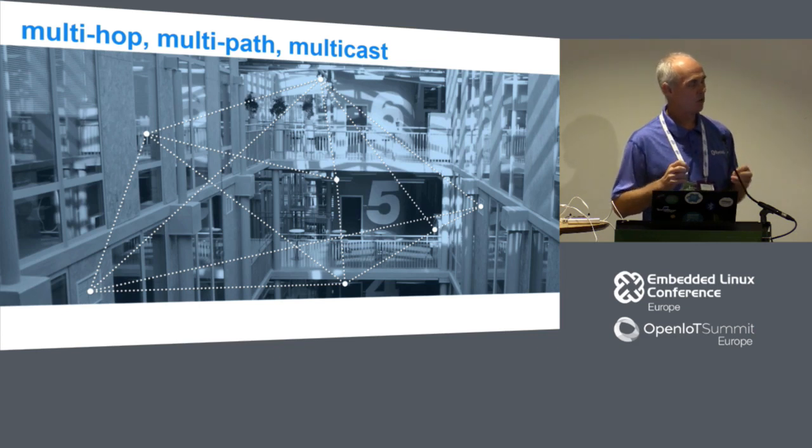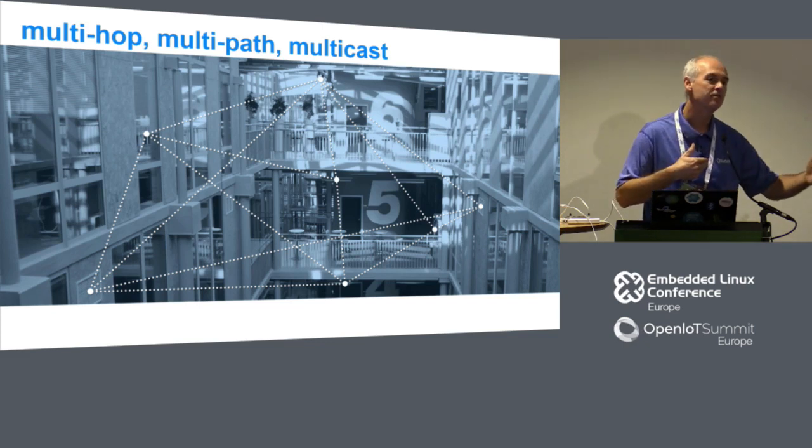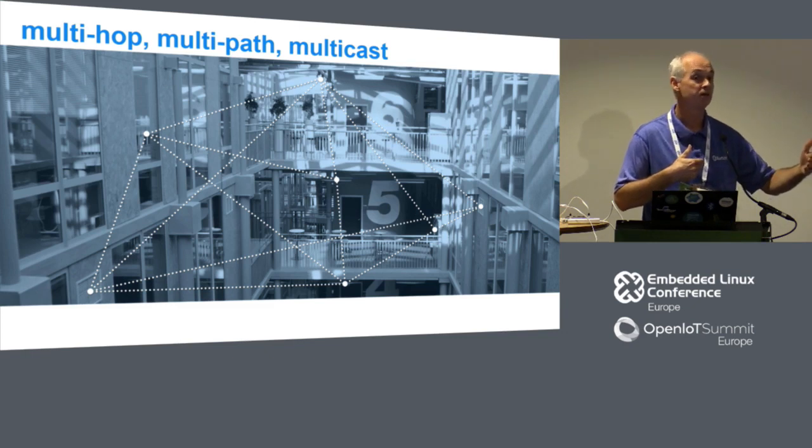And one of the benefits with multicast messaging is that you make incredibly efficient use of the radio medium with respect to the work you're trying to get done in the network. The number one constraining factor in scaling a wireless network like this is how efficiently you use the radio medium. We have a number of frequencies we're going to be using. We use 3. And how long you transmit on a given frequency is how long you're stopping other devices from transmitting, because you get collisions.